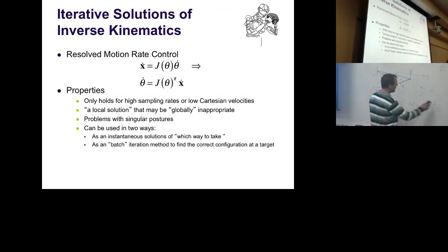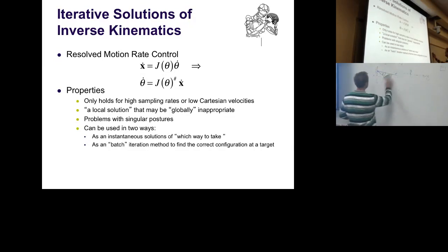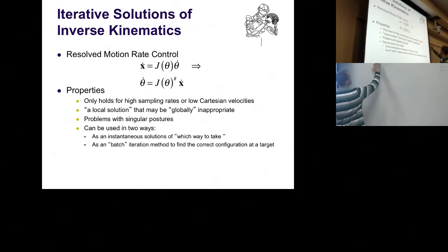And this is actually an important topic. We're going to something now which is called differential kinematics. It's a very useful topic to know about. So we have our original x, without a dot, x equals f of theta. So this is the direct kinematics. What I'm going to do now is take the first derivative. So this is x dot with respect to time. And this is, if you remember, df d theta times d theta dt. So partial, but then absolute. So this is the Jacobian, which is a function of theta, times theta dot.